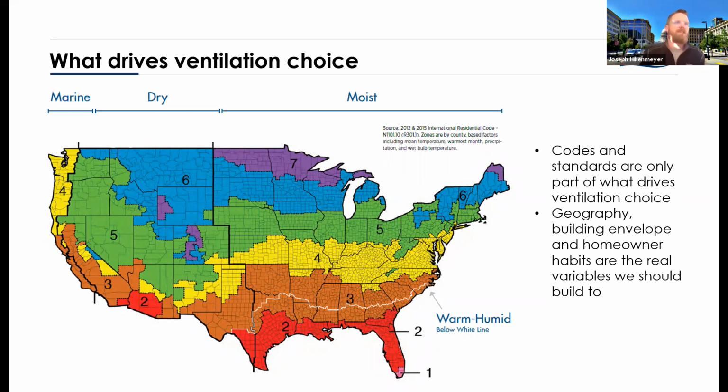And when you add up that surface area, you have much more of it. The more surface area it has to press against, actually, the less pressure there is, and that's a good point. I mean, there are 1-inch solutions that offer a higher MERV value, but no contractor is going to be happy if he walks into your house and sees it, because he's going to know what's happening to that system. You've practically stuffed a piece of cardboard in there at this point, right? There's not enough air going through there.